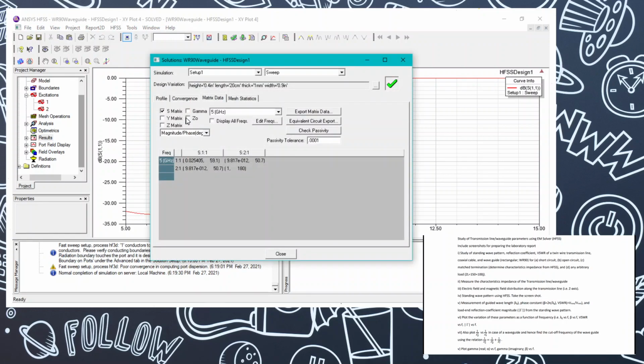That is, this will open, and you need to check this part. You can see the Z naught is showing right now, and at 5 the Z naught is 243 resistance, and this is the reactance. As you can see, the characteristic impedance is being calculated, and you can put this value in port 2 to get the different field distributions at the characteristic impedance condition. And you can put any arbitrary load at port 2, which is a lumped port.